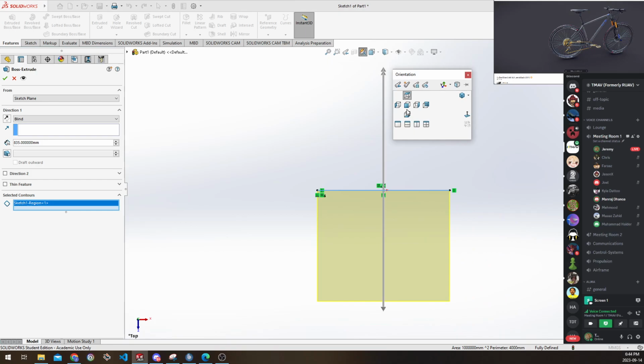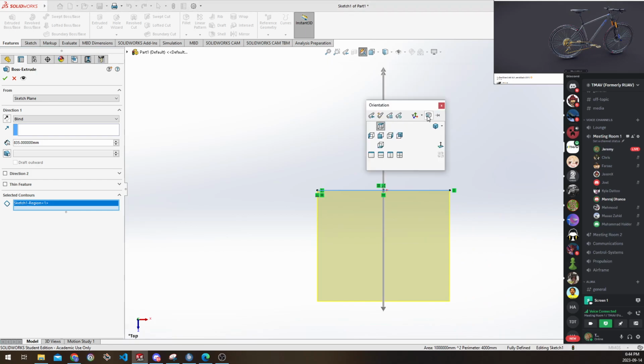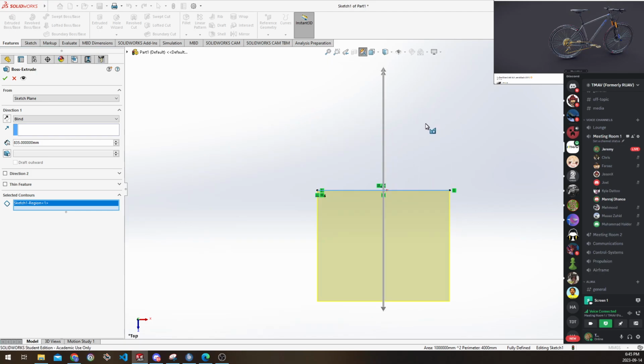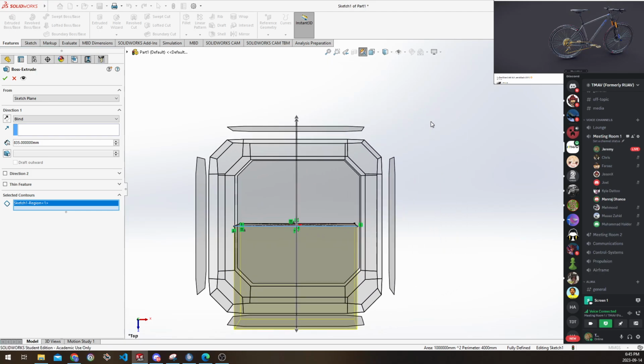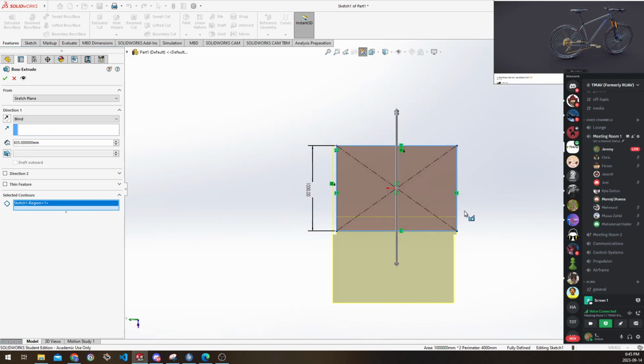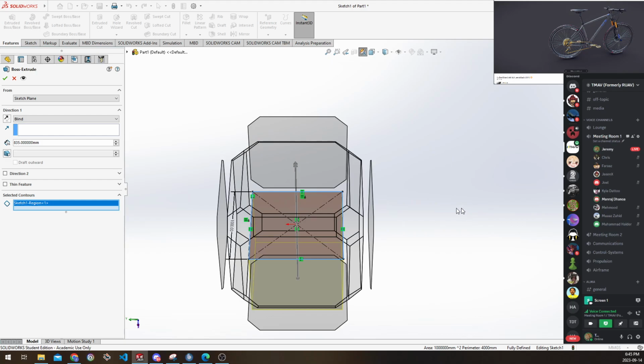I think there's another button, I can't remember, I think it's this thing. Yeah, so if you press space and you click on this guy up here, view selector, I think it's control spacebar, it'll pull you into this view, so you can actually click corners as well if you want isometric views or angle views. Right, so that's control spacebar.